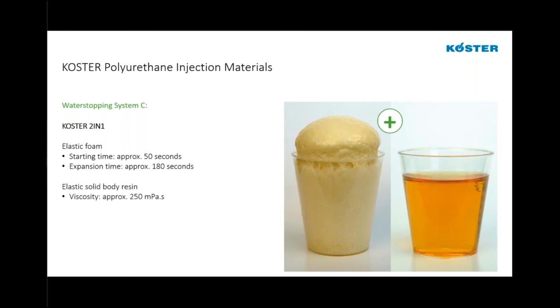We re-inject the same material into the same ports. After that water has been used in the reaction, the crack should be fairly dry, and they will react as a solid body resin again to encapsulate that foam and give us a long-lasting system with one product where we're injecting the same product twice into the crack without needing to change over and clean the pump between